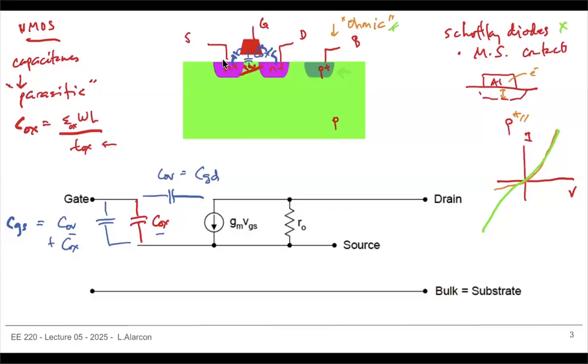Let's redraw. Right. So if this is your gate, and you have your source and drain, then it's only going to be dependent on the width. Right? That's the width, and that's how much overlap you can get. The capacitance between that gate and the drain, or the gate and the source. Right? So those are the main capacitances that we see.